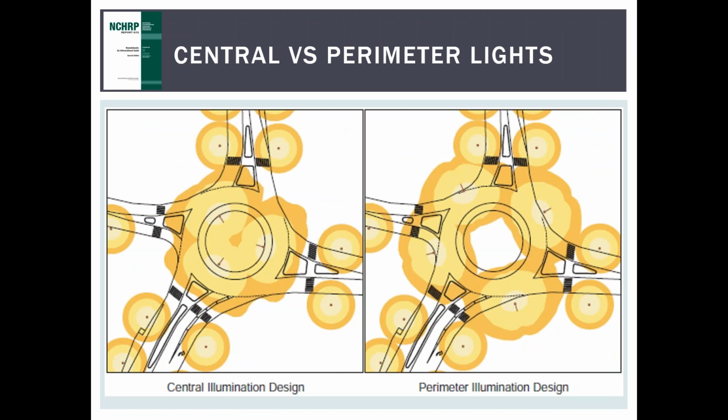Roundabout lighting can be achieved by installing lighting within the central island or around the perimeter of the intersection. The IES design guide for roundabout lighting recommends lighting be placed around the perimeter of the roundabout and at locations on the approach side of the crosswalks. Perimeter illumination provides the most optimal visibility within the key conflict areas and the visibility of circulating vehicles to vehicles approaching the roundabout. In addition, the vertical lighting levels in the crosswalks cannot be achieved unless approach lighting is used.